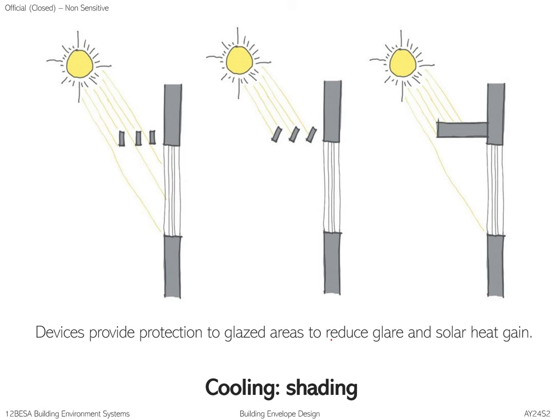So if you are thinking about the design of your studio project, how it looks, have you all ever considered sun shading devices? Probably not yet, right? You will notice that around the island, HDB has incorporated quite extensive use of sun shading devices, and mostly they will use a solid ledge in front of the windows. This is a very important mechanism to protect the glazed areas, to reduce glare and solar heat gain.